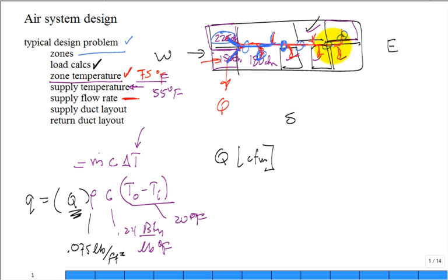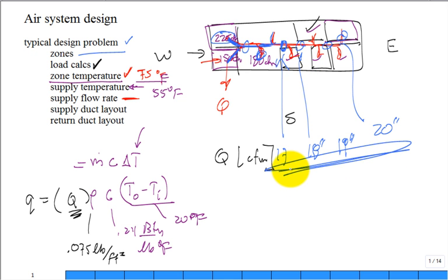The new engineer says, oh, I'll tell you what we'll do. We'll have the diameter of this duct start out at 20 inches, then go to 19 inches, then 18 inches, then 17 inches, and don't ever design something like that. There's too many step downs, too much crap on the construction site. They just need a couple of sizes, and they're going to run it, change it, run it, and be done with it. Don't be too tricky in your design to optimize. Have a few parts and make it transition.